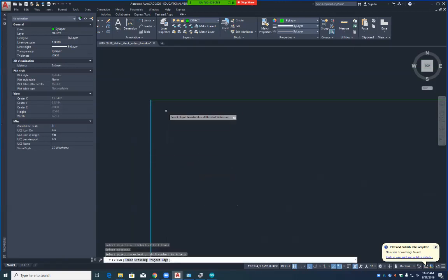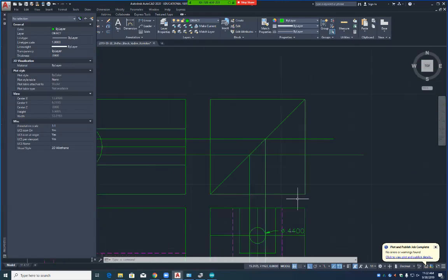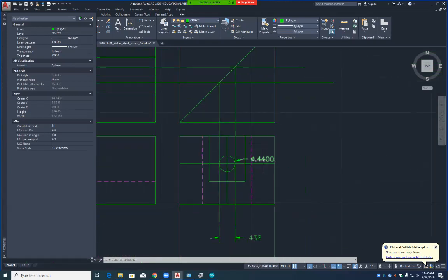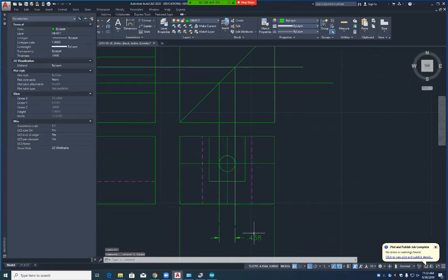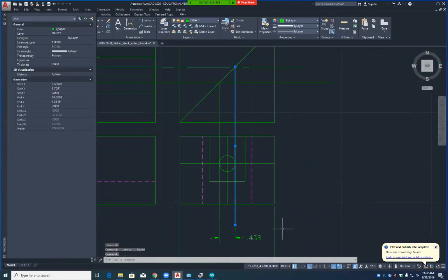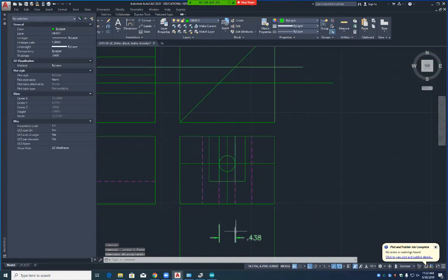Down here at the bottom, you see where it says distance and angle. What's our chamfer measurement size? It's 0.31. 0.31 by 45, right? Yep. So what's our other chamfer distance size? If it's 0.31 one way, if it's 45, what's the other chamfer distance the other way? 0.31. So we can either use distance or angle. Which one do you want to use? The distance or the angle? Distance. Okay, come down here and click on the distance then.